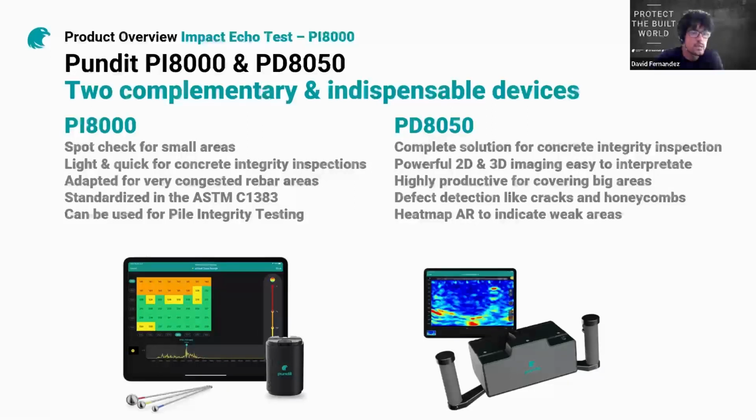And it's really good when you have areas with a lot of rebars, because this methodology relies on the impedance, as I said before, and the impedance of the steel is similar to the impedance of the concrete. So if you have a lot of rebars, the wave will travel through those rebars, and then you will be able to detect voids below those rebars. So this is a very useful tool for that.